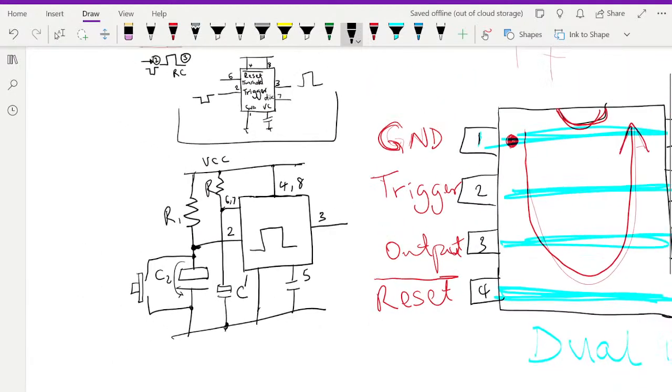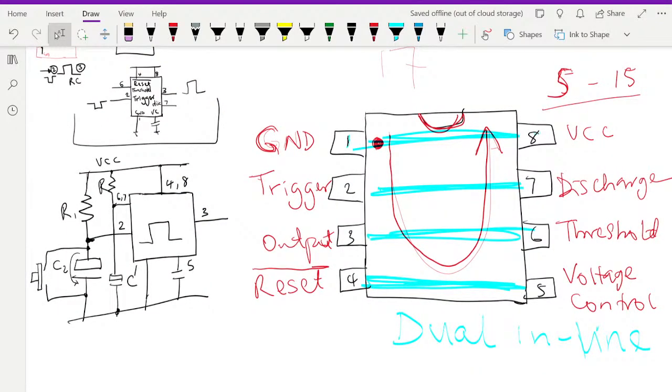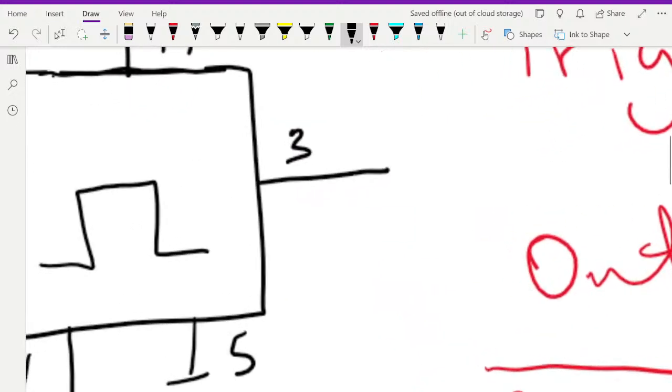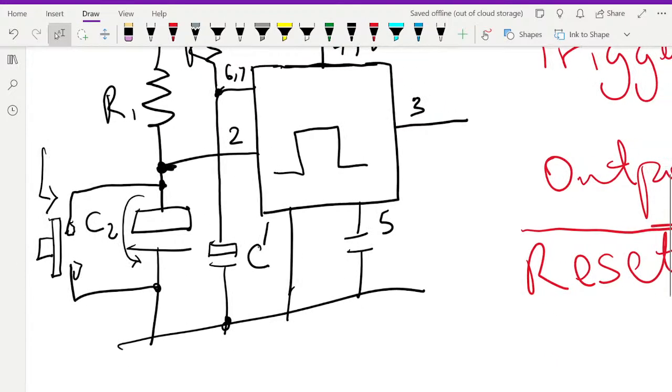When you push it and you apply, I'm trying to make this move, but apparently I'm at the end of the board. So when I apply a force, so I'm closing the circuit, this switch, and then the capacitor is shorted to ground, and then my monostable period starts. But if you want to build a power up one shot system, you want a capacitor there. So the moment you boot up, there's a jitter that goes through the capacitor. The capacitor shorts momentarily to ground, and then the capacitor charges up, so it opens up again. But that moment starts this monostable period here.